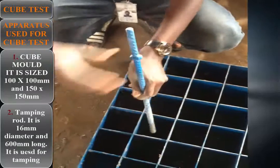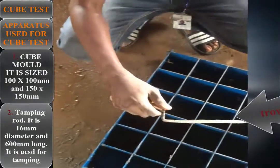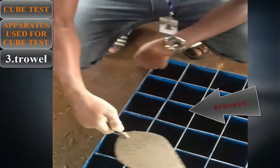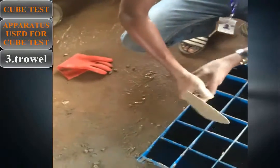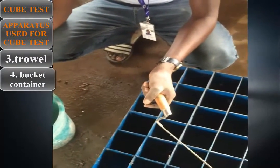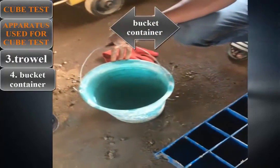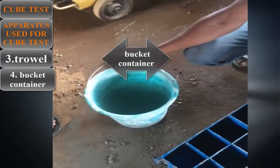The third apparatus is the trowel. It is used for picking up mortar or the mixed aggregates into the cube mold. The fourth apparatus is a bucket container. The bucket container is used for carrying water, or it can be used to pick samples of the mixed aggregates.